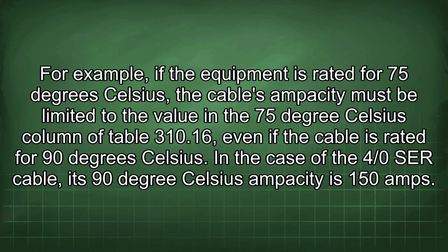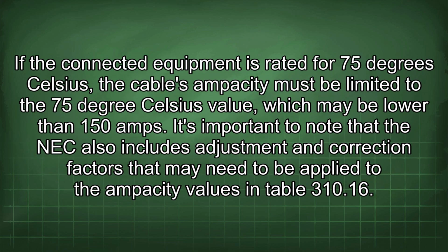In the case of the 4/0 SCR cable, its 90°C ampacity is 150 amps. If the connected equipment is rated for 75°C, the cable's ampacity must be limited to the 75°C value, which may be lower than 150 amps.